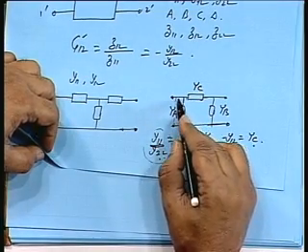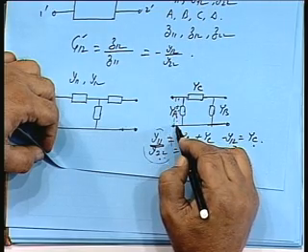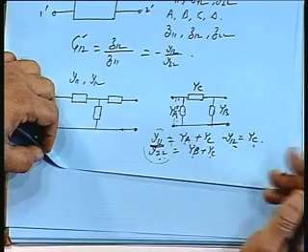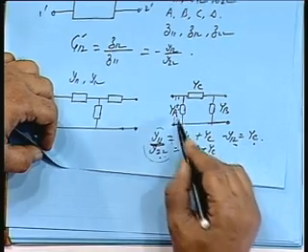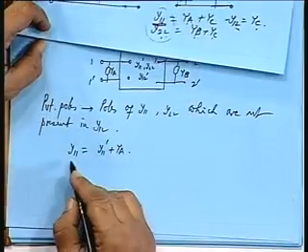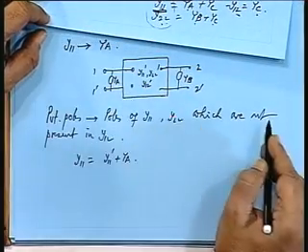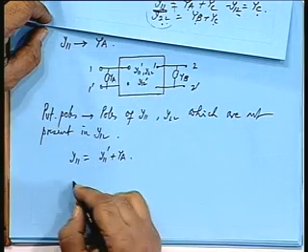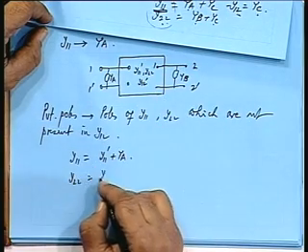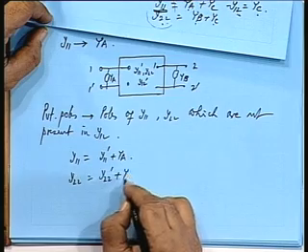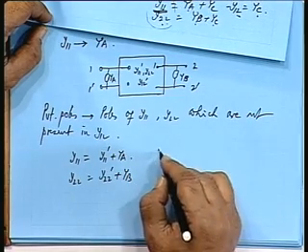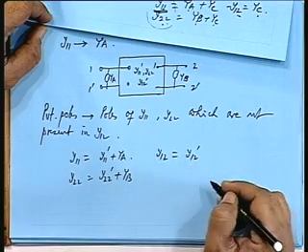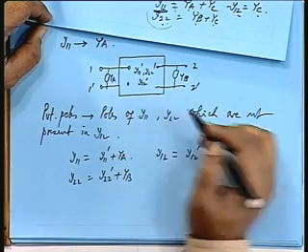If I have another additional admittance here, that will be changing only Y11, that will not be affecting these two, because it is only YA which is getting modified. So, Y11 will be this additional element plus whatever is the Y11 dashed here. Similarly, Y22 will be Y22 dashed plus YB, but Y12 will be Y12 dashed, that remains unaffected.